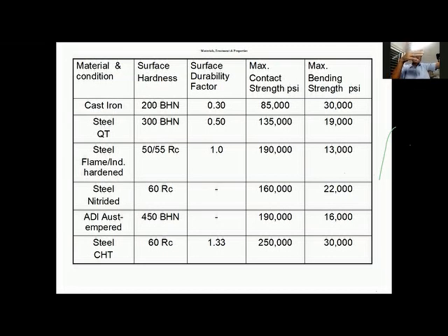As I mentioned in the earlier meeting, surface hardness of 60 HRC corresponds to 300,000 psi surface strength. If you take a normally designed functional gear, it will have a requirement of only 180,000 or 200,000 psi strength, whereas this goes to 300,000.